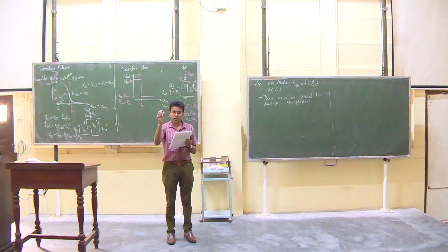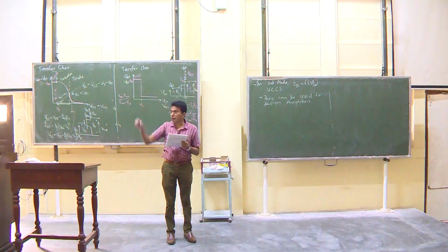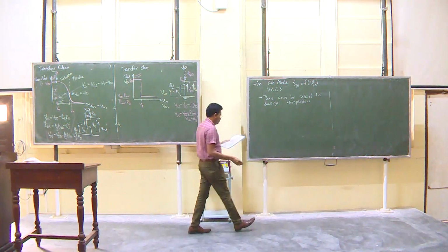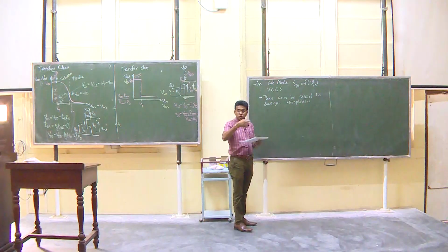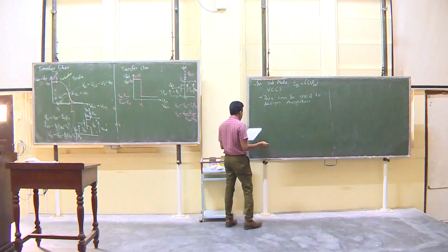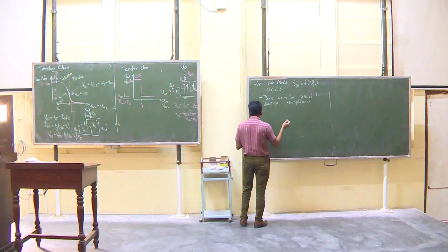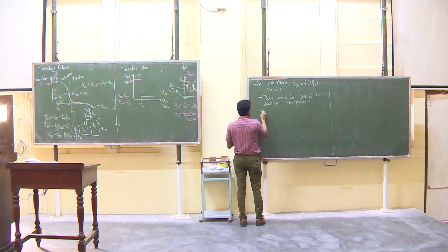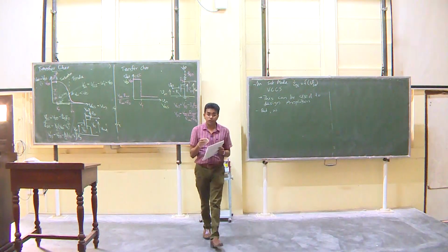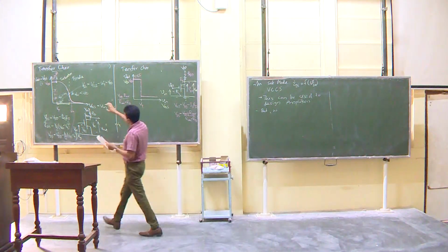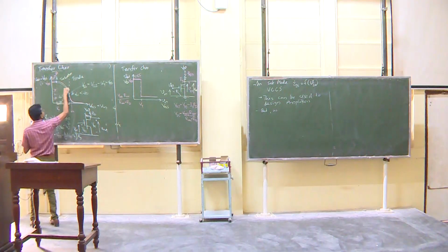By changing VGS, I am changing a larger current I. Okay. By sending this current through a resistor, you can convert that into a voltage. But in order for this to be used in this form, that equation is valid only in this region, right?